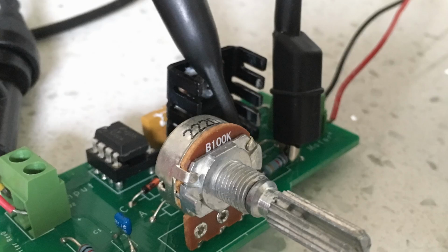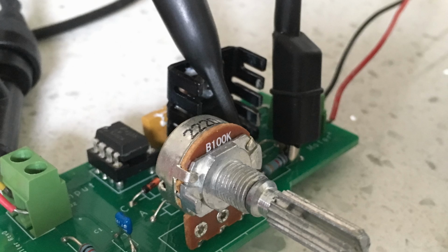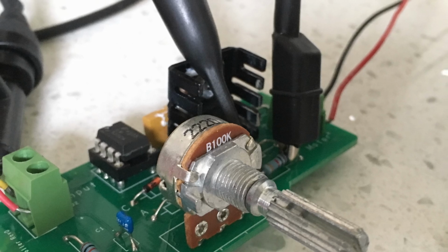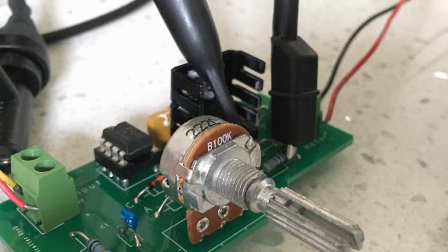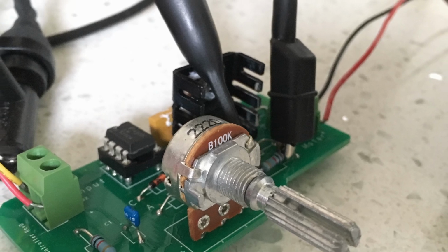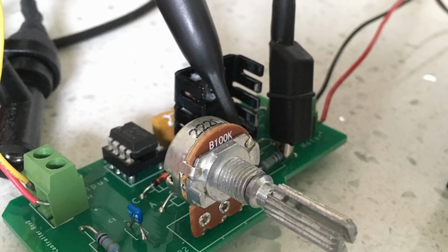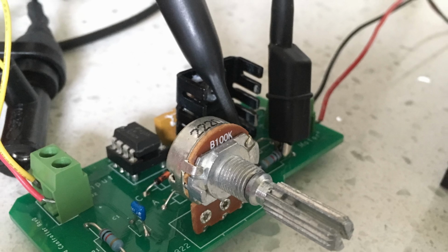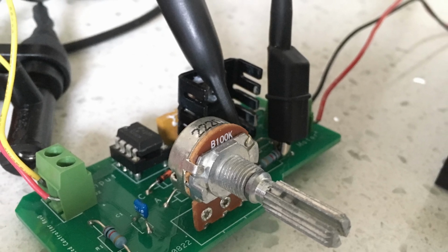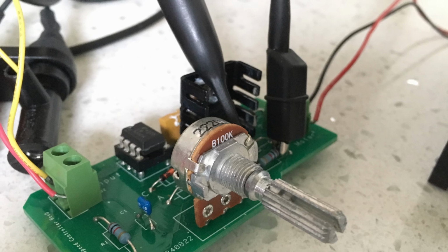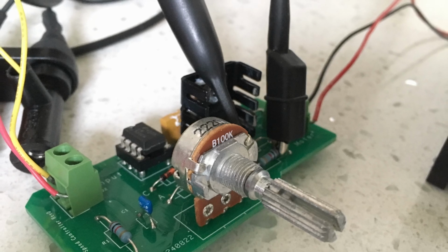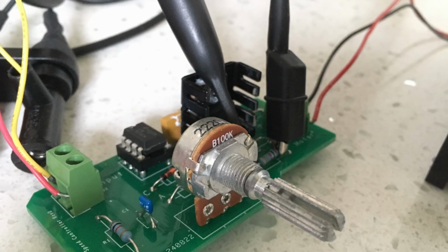I've used an N-channel MOSFET in a TO220 package for this demo. The output from pin 3 of the timer is connected to a resistive divider of 100 ohms and 1K as shown. The motor leads are connected to the drain and the 12 volt supply. As a freewheeling diode, I've used a 1N4007 as shown in the schematic. I've designed a simple PCB and soldered all the components as discussed.